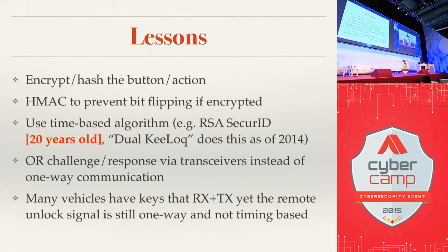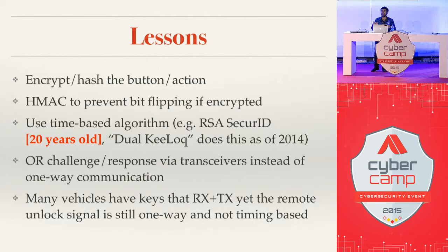And the lessons that we've learned, there's a couple things. If you're designing a system like this, there's a couple things you want to do. First, you want to encrypt or hash the information that you have. You don't want to just have a rolling code and then a field that says lock or unlock. All of that information should be encrypted or hashed together so that they're intrinsically tied together so that you can't abuse it if someone is ever able to recover some of this information.